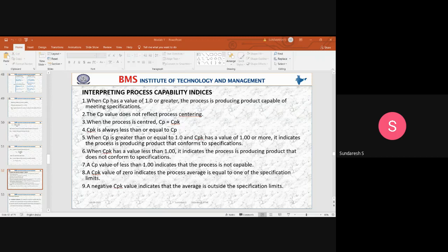My question is, definitely there will be some difference, I agree, but why will that difference come? What are the reasons for variation taking place in the dimensions of the components? If I want to manufacture a shaft with a diameter of 20.5 millimeter, and I want to produce around 50 such shafts of the same size, using the same machine and same operator, is it possible that all the 50 shafts will measure exactly 20.5? No, sir. Why is there variation? Same operator, same machine, same dimension, same material.